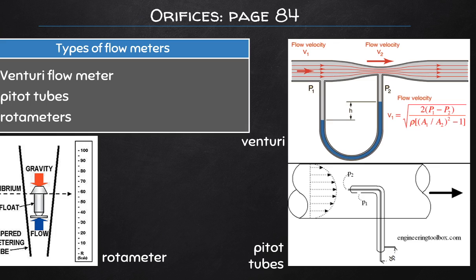Now considerations pertaining to the type of flow meter that is chosen are matched with the type of fluid material. So the fluid, what is the material that is being pumped around? What are the conditions, the operating conditions? What is the flow range that can be expected? If you have too high a flow or too low a flow, the flow meter might not work as required. What is the required accuracy? As well as what are the other types of concerns, like are there any environmental concerns such as hygiene? Are you working in a food factory, for example?